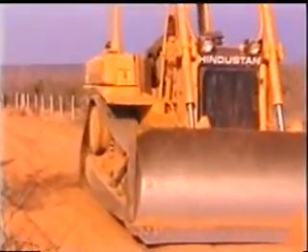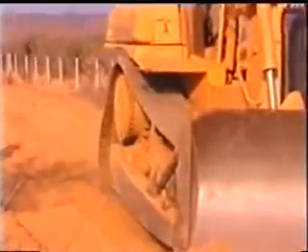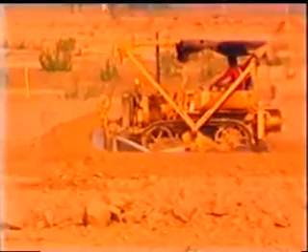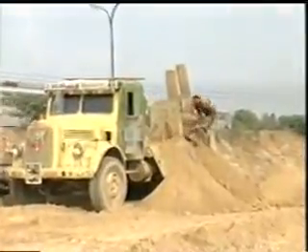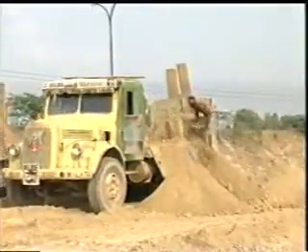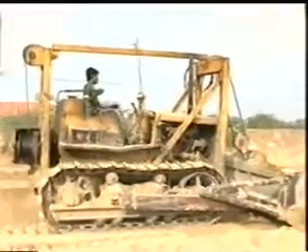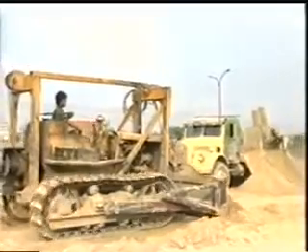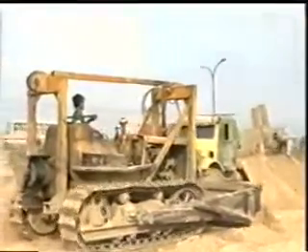Once the ground is leveled, it is either excavated or its embankment is raised, depending upon whether the road is in filling or in cutting. This stage also involves transporting the soil from the borrow pit and uniformly spreading it in layers with the help of bulldozers or scrapers.